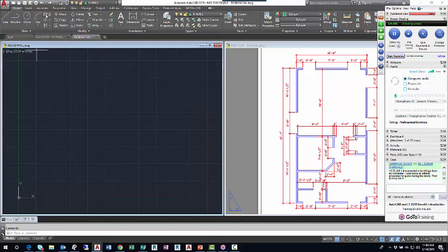In the upper right corner of the draw panel, left click rectangle, and, habitually moving the crosshairs into the drawing window, the command prompt says specify first corner point. I'll type in 0, 0, enter. And that's a little less crucial right now, but if there's any potential you're going to share this drawing with other drawings, it's a good idea to be on top of where your insertion point is, and relate it to 0, 0 to the extent you can. So I've started at 0, 0.